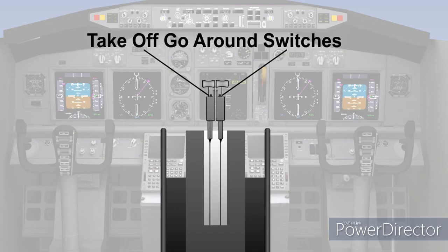It would be normal for this type of aircraft to use the autothrottle to manage the thrust for the takeoff, climb, cruise, descent, and approach, up to the point the pilot takes control for a visual landing. If an auto-land is being carried out, then the autothrottle will remain engaged up to the point of touchdown.